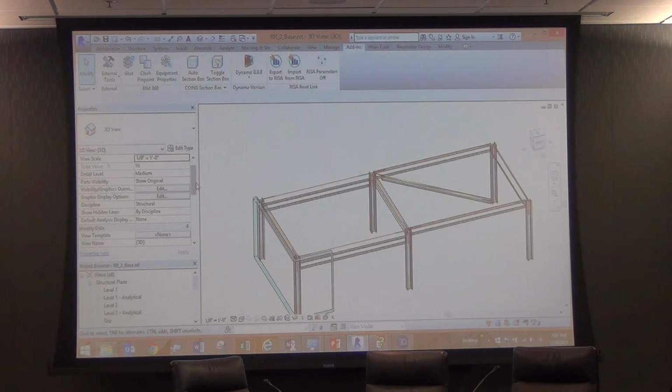Now, the problem with that is that everything rotates to be aligned with that. So now all your girders are rotated at 1/4 of an inch per foot slope, and that, in my opinion, doesn't solve your problem. So I wrote an add-in where you model your roof as a floor, and then you can run this add-in that essentially says,